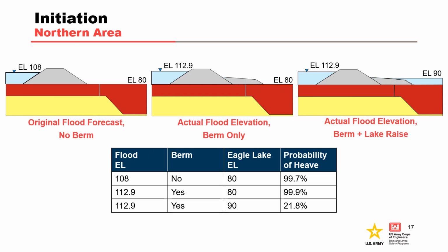A blanket theory analysis was performed by the Risk Management Center after the 2011 event to gauge the effectiveness of the flood fighting efforts to prevent heave. This analysis included a probabilistic first-order second moment analysis to determine the factor of safety against heave and obtain a probability of heave for 3 different configurations of flood loading and mitigation measures.